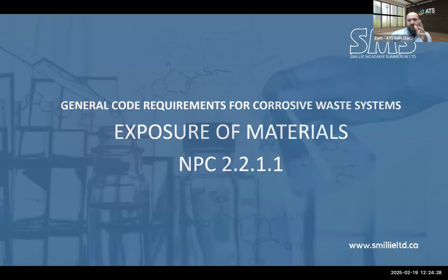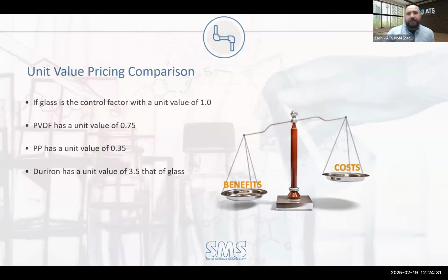So just to take a little pause there as we finish off recapping the glass aspect. Yep. The borosilicate glass, widespread usage, one of the few that is actually available for the vertical risers if they're using it there. Correct. But there's a little bit of a cost bump associated with it. Yep. Whereas, like you mentioned, if you're doing retrofits, and converting a classroom in a school is a great example, it comes up all the time, you could, depending on whether or not it's sprinklered, you might have more options.